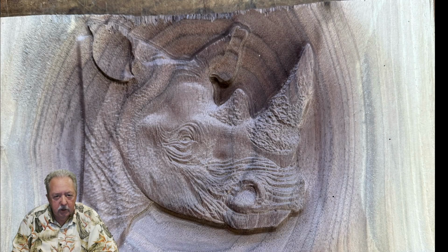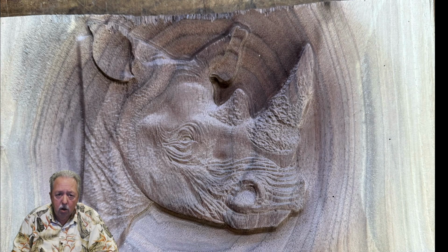Well, I got the carve finished, and overall it looks pretty good. You can see a little tear out up there on the top. That was probably because of how close I placed the Rhino and the way the bits were going across there. It might have even happened during the roughing pass and I didn't notice it. But overall it turned out okay. I later took a little sanding wheel from my Dremel and I smoothed out that edge. You can see that initially the carving doesn't always pop. It will pop more if you have lighter wood and if you have deeper carvings.